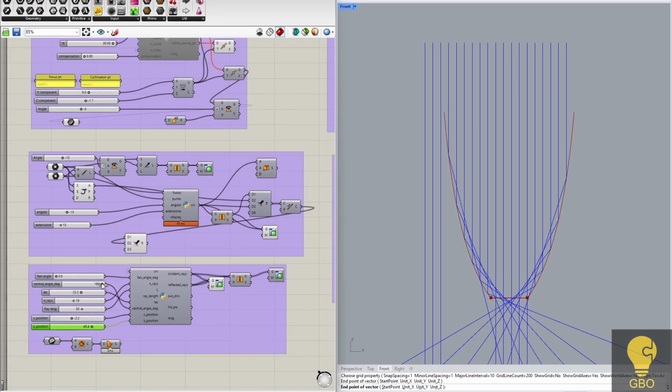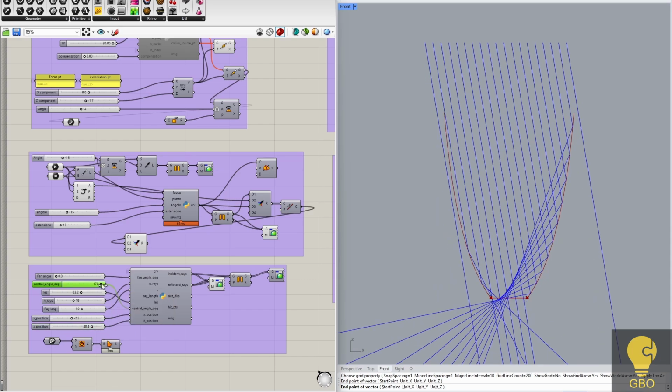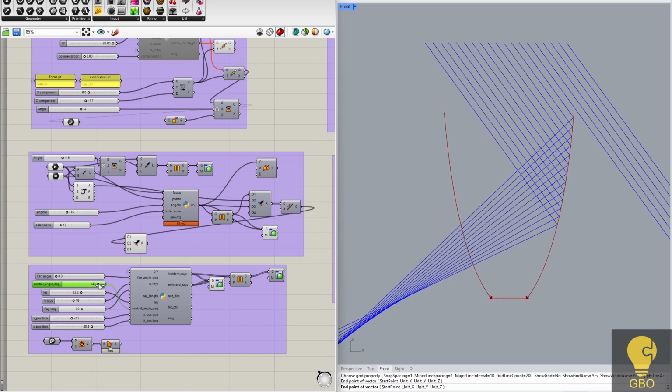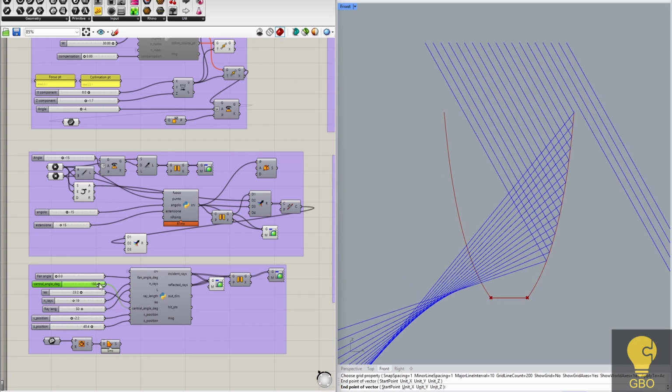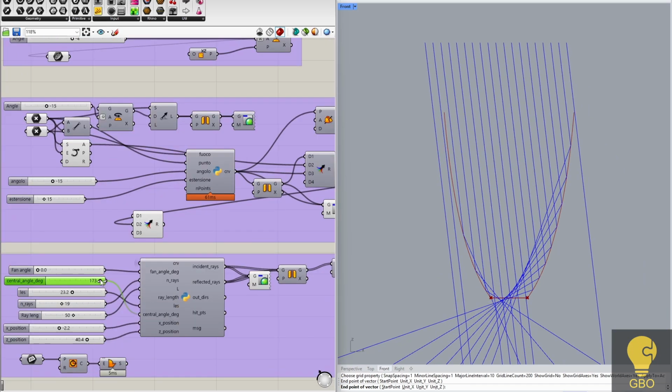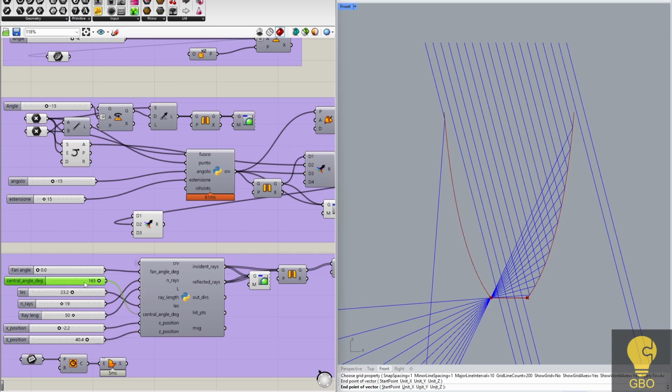Sunlight, for our purpose, arrives essentially collimated, and the problem is to collect it and concentrate it into a small receiver. If we say that we want to accept light arriving within plus or minus 15 degrees, building a reflector of this type with a sensor in the central region maximizes collection, because every ray that arrives within that angular range is delivered to the central zone where the receiver sits. The acceptance angle of the collector and the output angle of the collimator are the same number, seen from 2 ends of the same device.